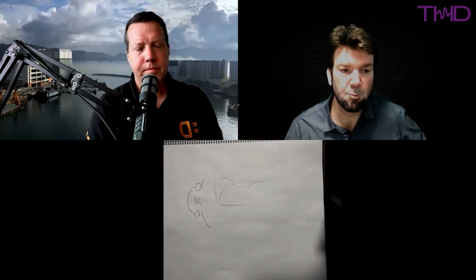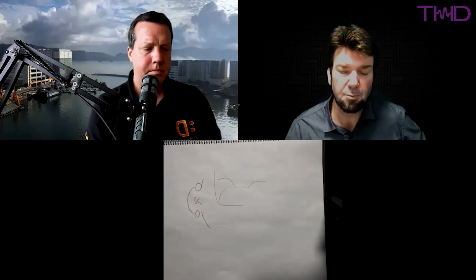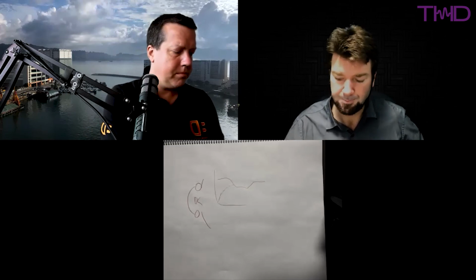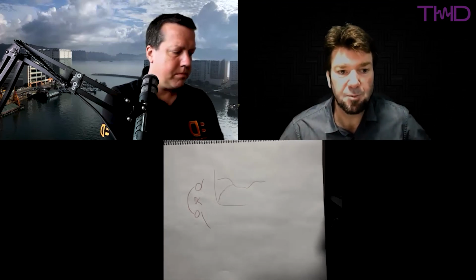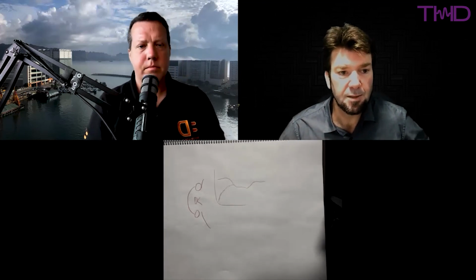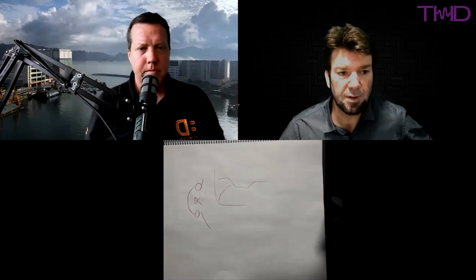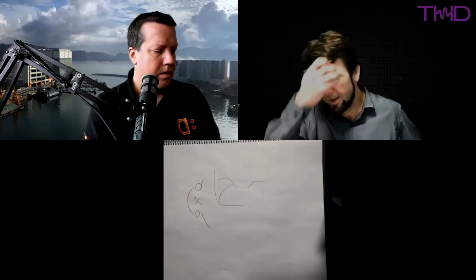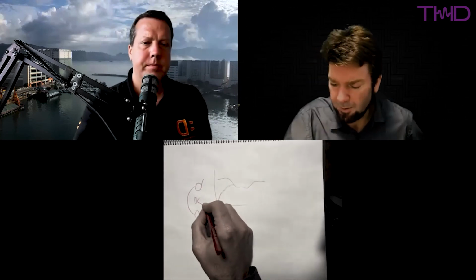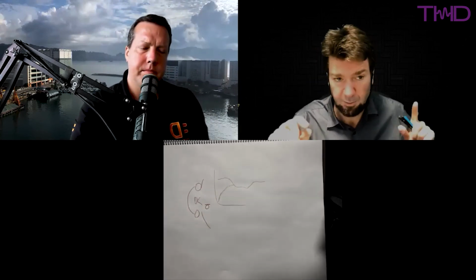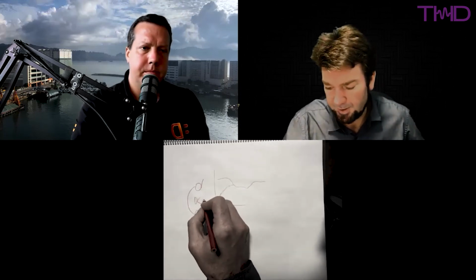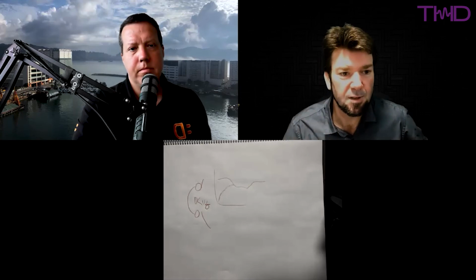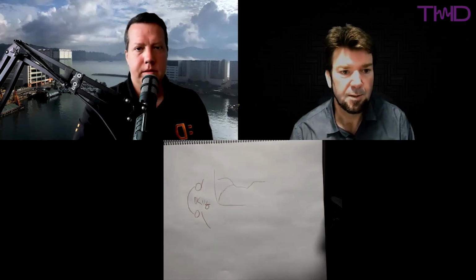Okay. I think it's mostly for a feed-forward system. You don't do that. Well, you could do it for feedback too, I guess, but it's mostly for a feed-forward system, and it's trying to compensate for those changes, probably mostly in terms of sealing into the head, which have a huge impact on feed-forward. Okay. Now, how you actually do that, I'm not entirely sure. I think you have a feedback microphone, which you also use as a measurement microphone to sense that speaker response on the fly.